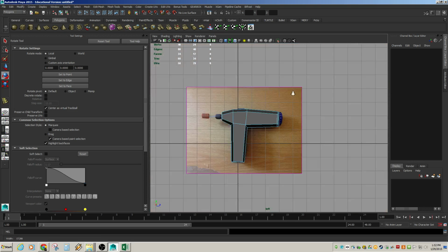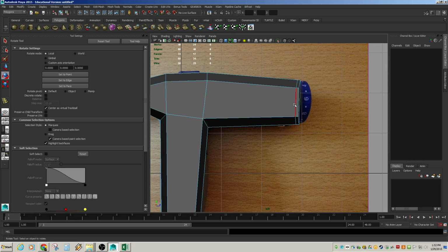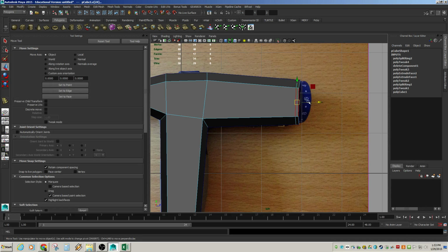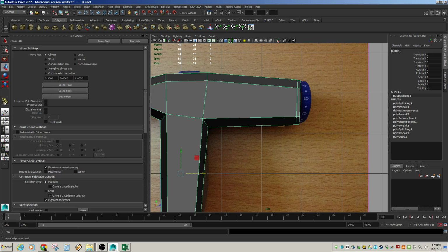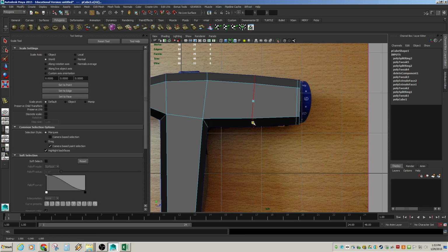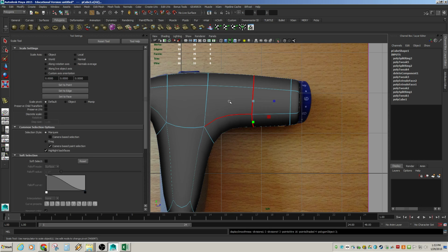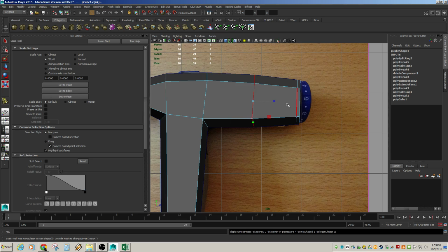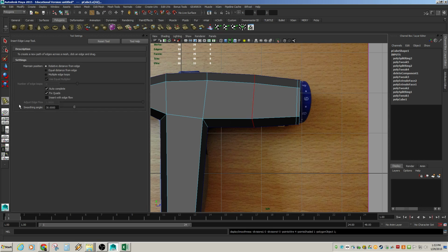Right, and now I can go back through here and do that sort of editing all across the entire model. Of course, I can continue to do all sorts of inserting of edge loops. The problem with some of this is in most cases with inserting edge loops, you insert the edge loop, and then you have to do some work to make that edge loop the right shape that you want, right? And we're getting a better result now, but this is a little extra step. Sometimes it would be nice if it would just insert the edge loop the way you wanted it to look.